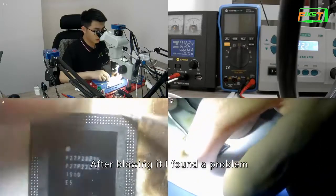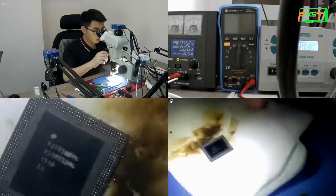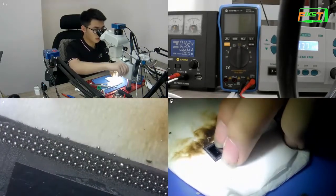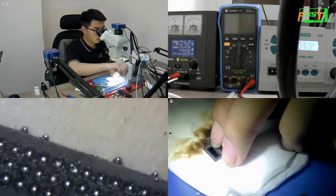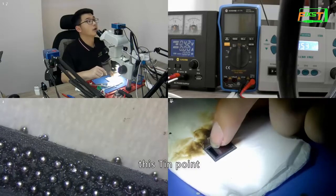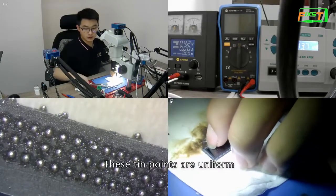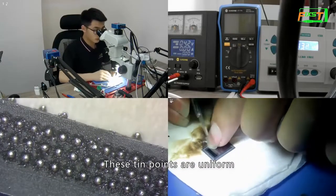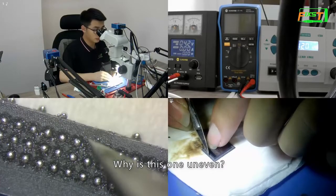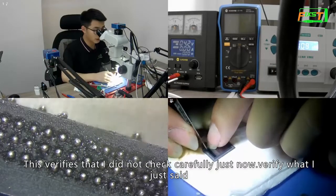After blowing it, I found a problem. See this place. This tin point, these are uniform. Why is this one uneven? This verifies what I did not check carefully just now.